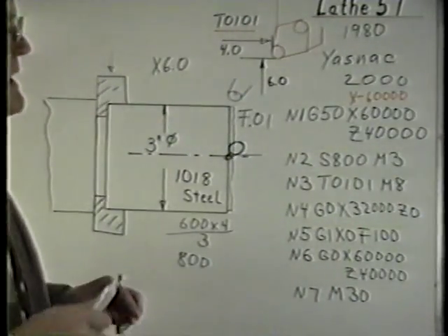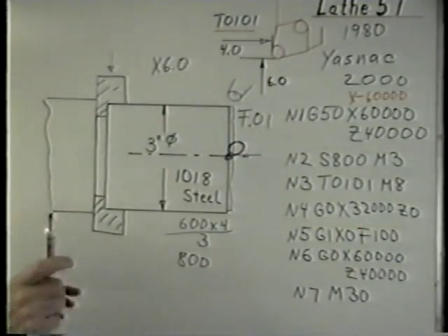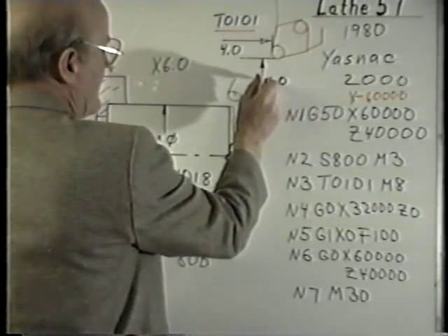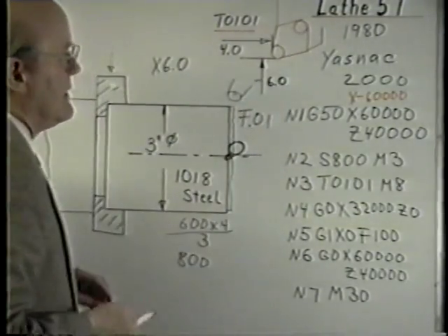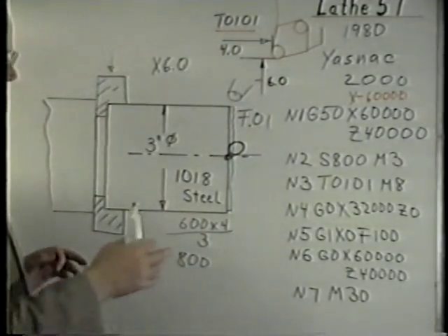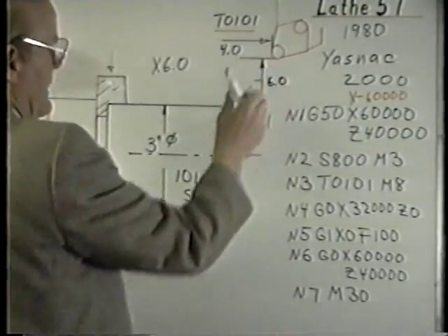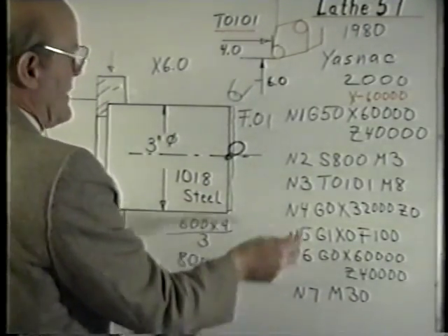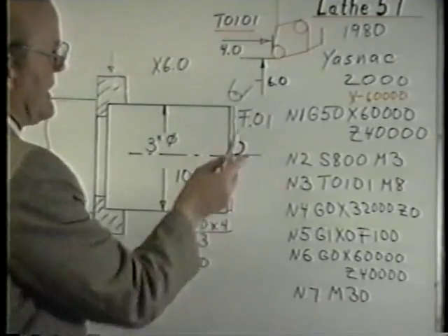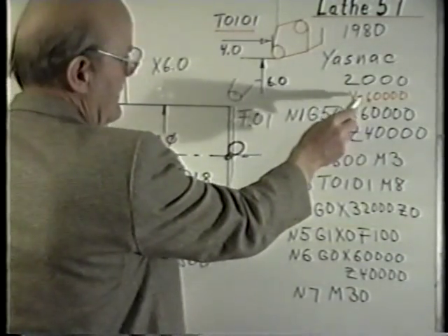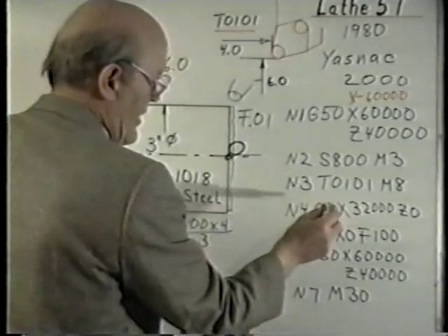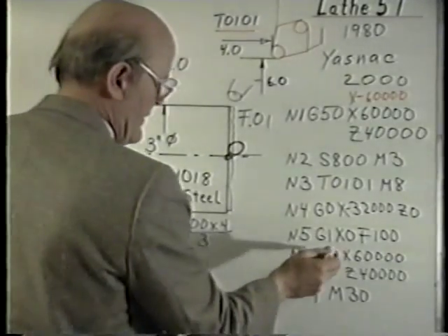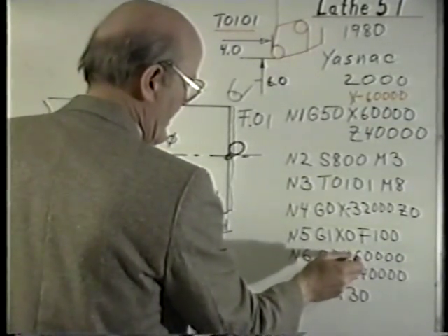There are a couple of possibilities that you should be aware of. Certain machines where these numbers, all the diameter numbers, had to be written as minus numbers. On the early machines, there were turrets in the front and in the rear. Typically, if the turret was in the front, that was the positive side. If there was a front and a rear turret, the rear turret would be written as a negative number, both for the G50, right there, also for all the dimensions. All dimensions, all actual part sizes would have to be written as negative numbers.